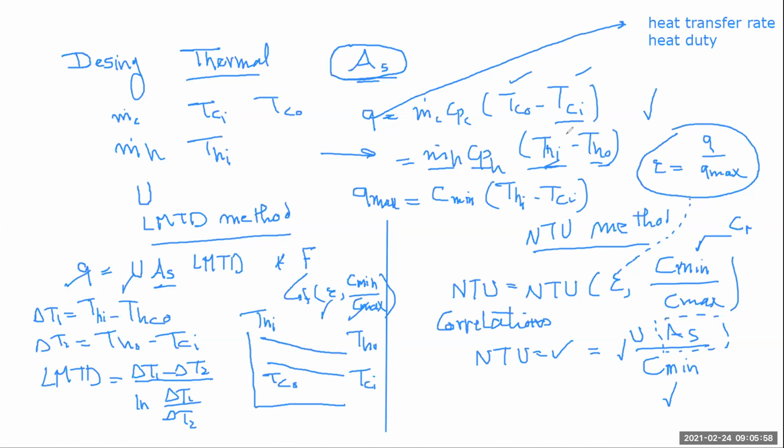Then what kind of materials used to be there? Previously, they used to use an alloy of copper nickel. You cannot use copper alone because the seawater is aggressive to the copper. So use an alloy, copper nickel, and then it becomes copper nickel 70/30, which means 30% nickel for the high temperature application, and 90/10 for the lower temperature stages.